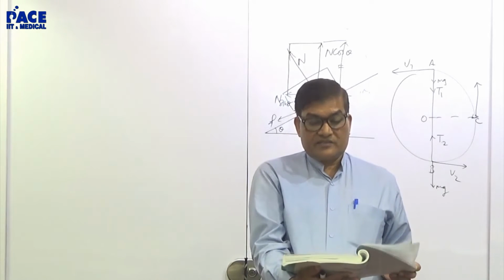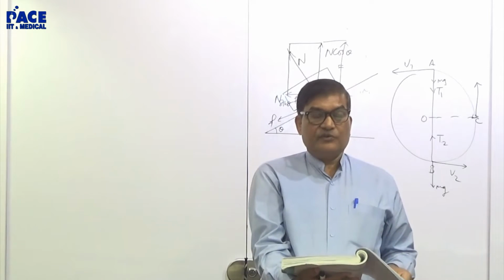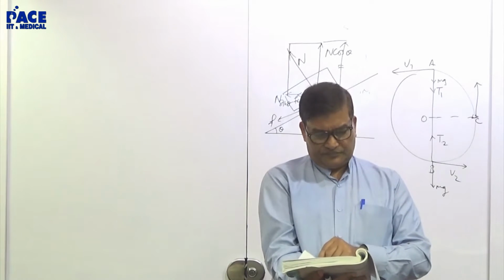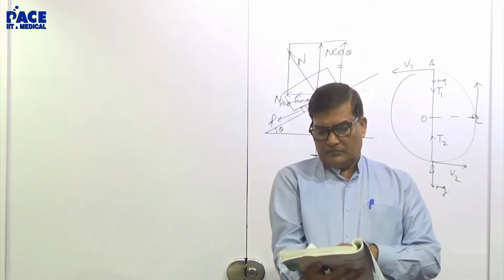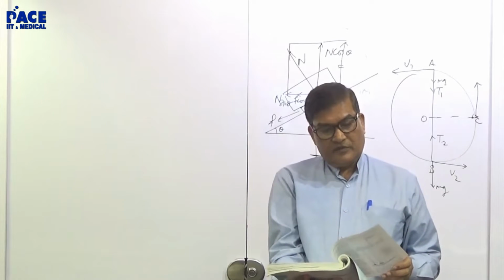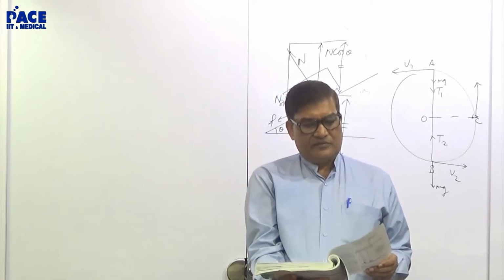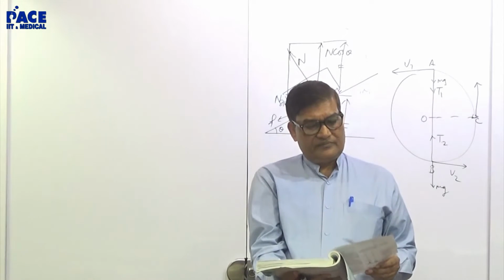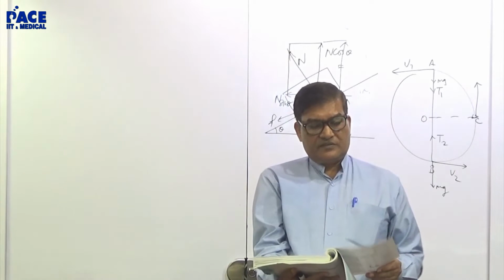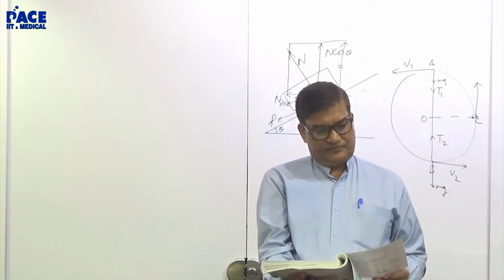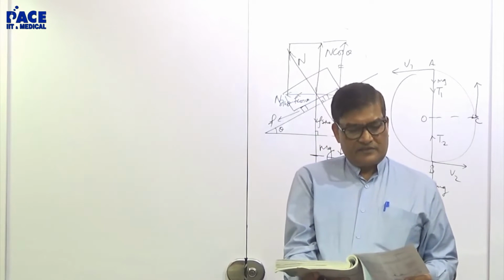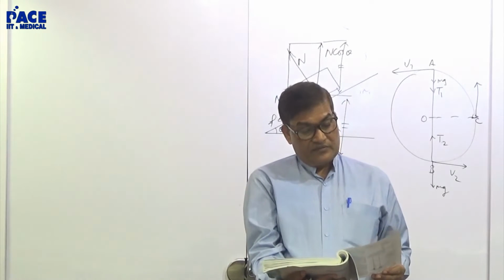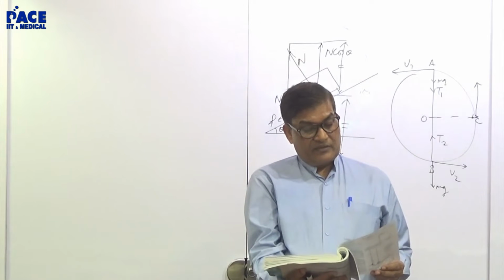In actual practice sigma is always positive, and its value is given. Then the very popular question, behavior of wire under increasing load, with diagram, that is the stress strain graph showing different things like elastic limit, permanent set, yield point, breaking stress and breaking point.